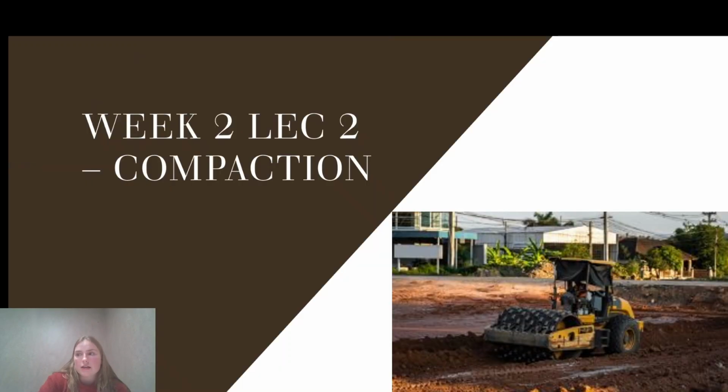And then the last thing I'm going to talk about is compaction. This is the second topic of week 2, and it's arguably the most important topic in geotech engineering. I might be slightly biased because this is one of my thesis topics and it's something that I'm looking at. However, construction projects can have huge issues and delays if compaction is not done properly. As a geotech engineer, one of the main things that you go do out on site is checking that the construction team have actually compacted the soil well enough for them to start building or putting the final slab on top of.